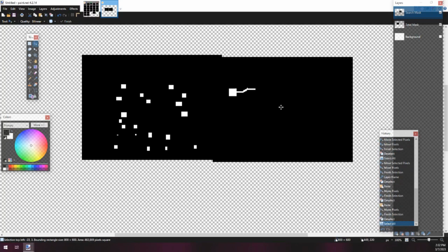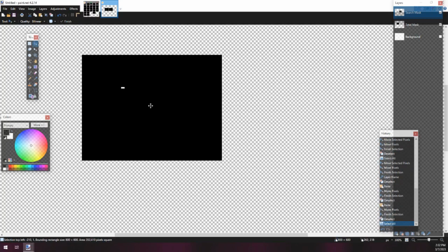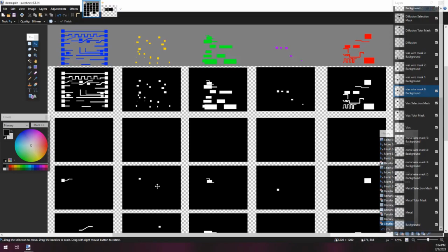And so what we then do again is overlay the two, and if there's any overlap, we know that there is a via connecting to that piece of metal, and we can start the process of adding it to its selection mask. From there, the vias layer is going to have a selection mask that basically looks like this. And we can then take that selection mask and go to the diffusion layer or the polysilicon layer with that exact same selection mask used as the new search mask, and we can find any bodies of these materials that overlap and add those to the selection as well.